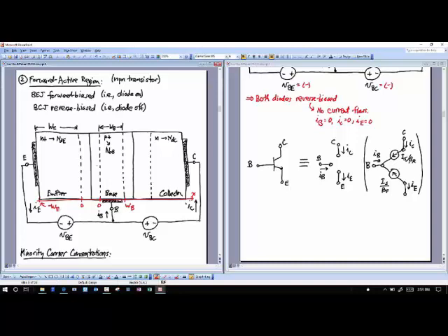But once they inject into this P plus region, they come against this depletion region. So I should say all of these things here, I'll use green for that. This right here and this right here, you know what these are. These are depletion regions. Straight from your understanding of diodes. Right? And so you know the type of charge you're going to get in this depletion region. If this base is P-type material, right, what kind of charge do I have in the depletion region on this side? Positive, negative? P-side will be negative, right.